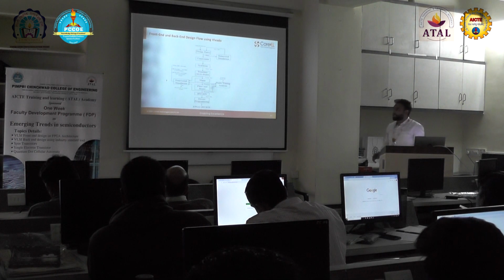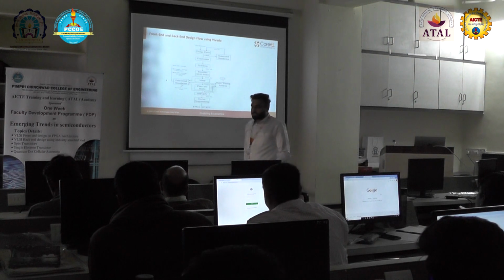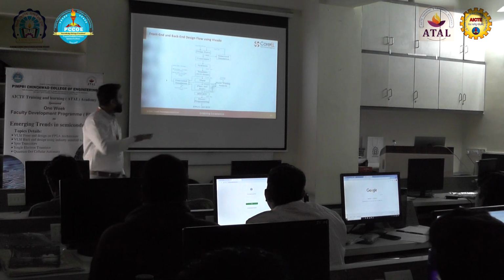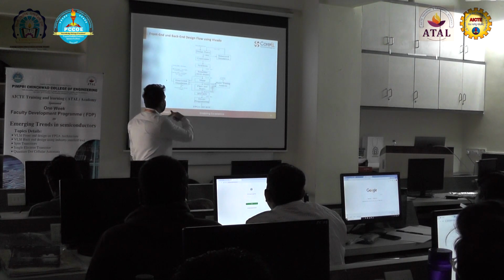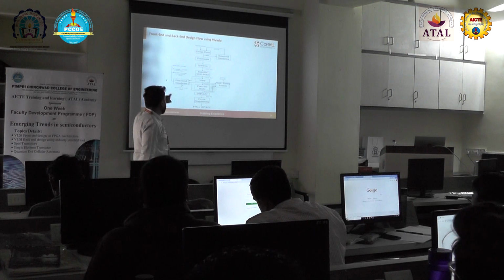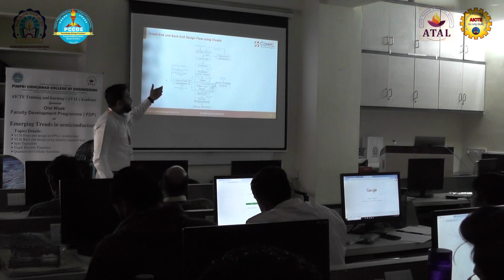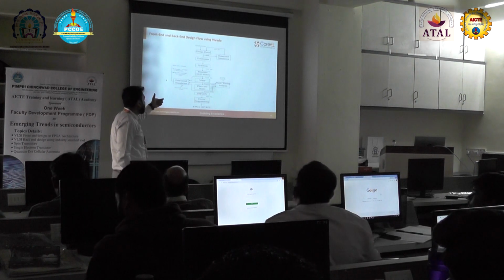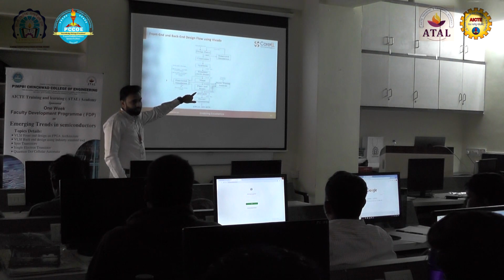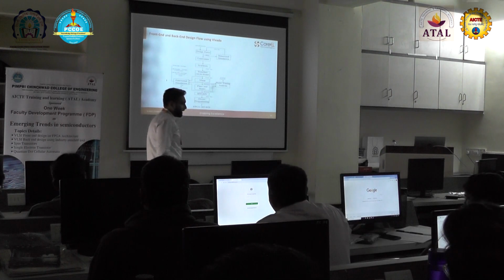In the functional simulation, we see the functions of the synthesis. Once synthesis is finished, after the behavioral simulation, we get the post-synthesis functional simulation reports. There we verify the function of the code. If it is not as per our intent, then we modify the design. Otherwise, we go to the next stage, the implementation stage.